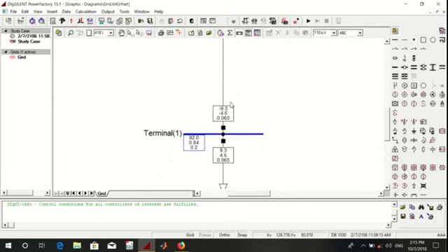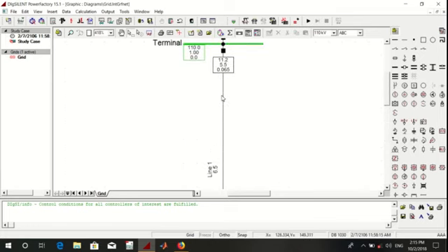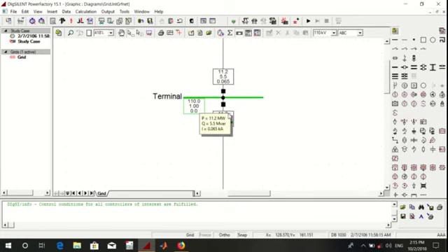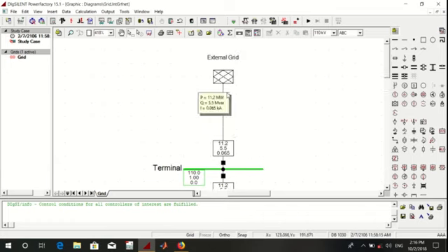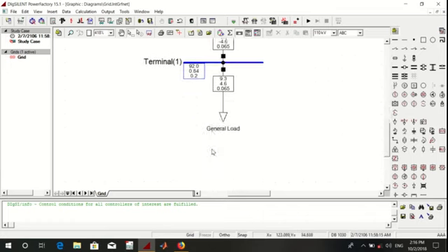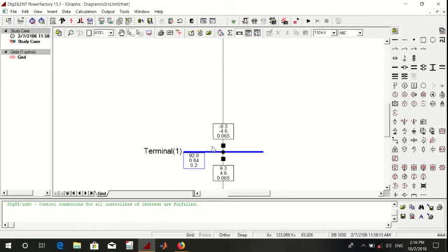And here the negative sign is shown, the same value with a negative sign, which means that it draws this amount of current and power from the system. This is our transmission line. Now at the initial starting point of the transmission line, our active power should be 11.2 megawatt, 5.5 MVAR reactive power, and the current drawn is 0.065 kiloampere. This is our required system capability that should fit this much load.